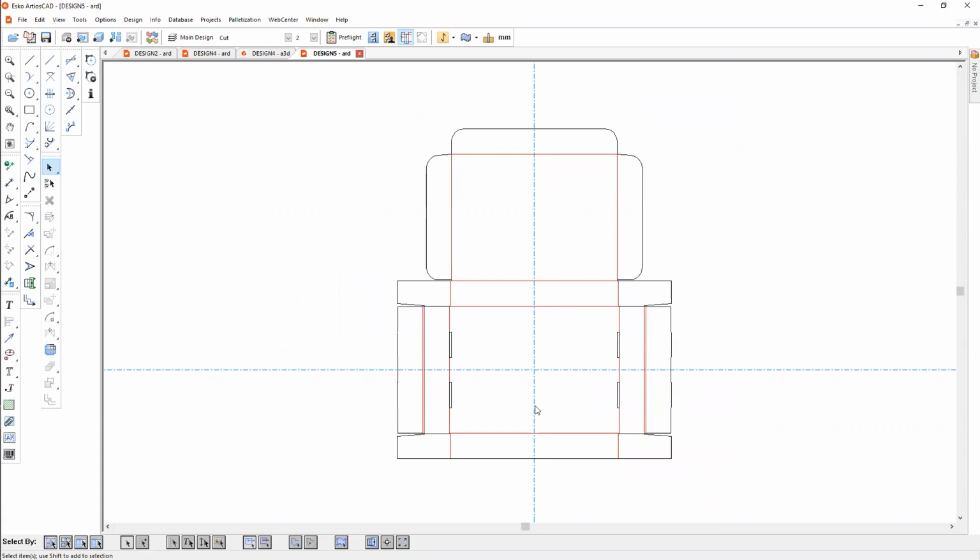So there's your die line. A lot of times this is where I'll start from. I'll use this, and then I'll build off of this, where we're either adding a die cut into this, or we're adding the insert, the whole parts inside. But this kind of just gets you running. From this point, you can take this 2D die line and pass it off to your graphic designer, and they will add graphics to this, and then they'll usually send those die lines back.